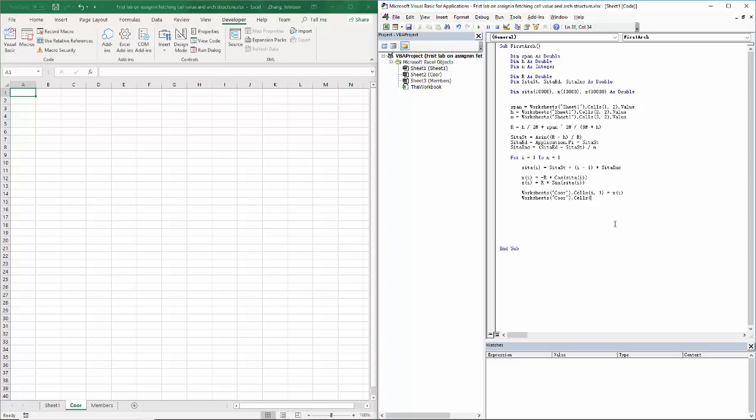That's going to be i dot z, stored in column number 2. So put the number 2 in here, equal to zi. So that's done. Once this is done, you close the iteration, this loop in here, with next i. So far, you have completed the part for coordinates.